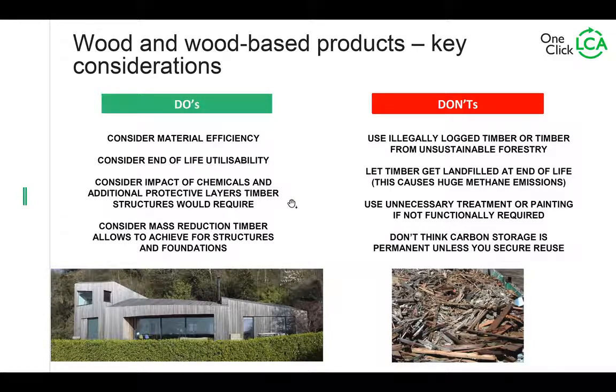So if you, for example, do timber floors, you typically need 2 gypsum boards for fireproofing. And then on the top, you need something massive. You can either use like 5 centimeters of concrete. Some are also using gravel just for mass because the step noise is very significant otherwise. And so on and so on.